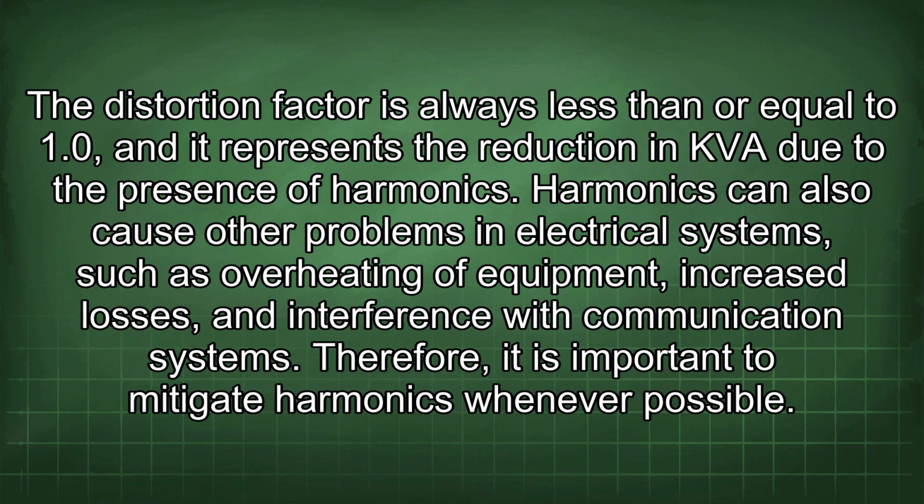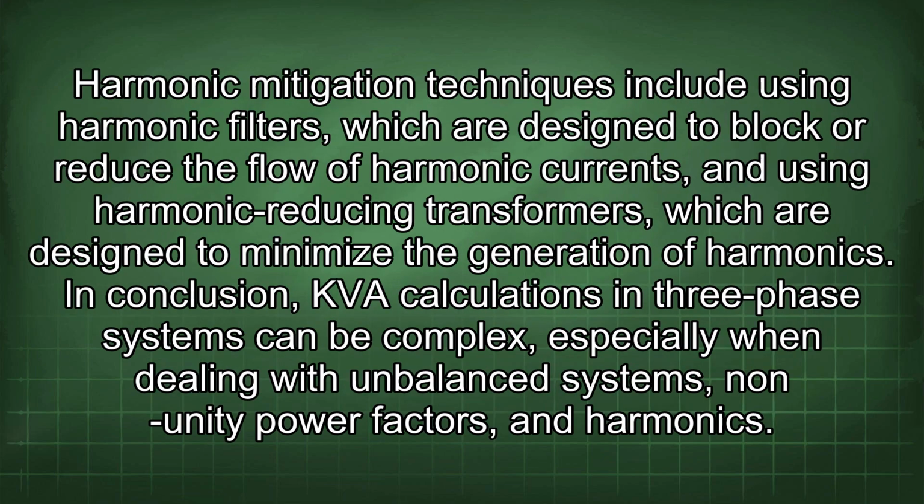and interference with communication systems. Therefore, it is important to mitigate harmonics whenever possible. Harmonic mitigation techniques include using harmonic filters, which are designed to block or reduce the flow of harmonic currents, and using harmonic reducing transformers, which are designed to minimize the generation of harmonics.